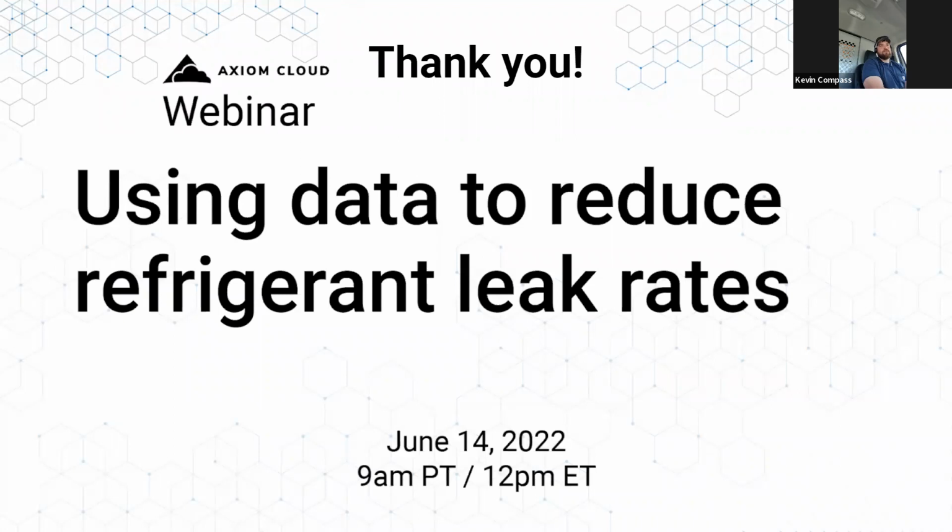But definitely receiver level. I mean, a digital switch, I think that whole era should be dead now. Analog gauges have come down so much in price that not installing it is just a huge waste of money, energy, and time. And Kevin, one thing you mentioned to me, I don't know if I misheard here, but it's possible now to install an analog sensor without pumping down the system.